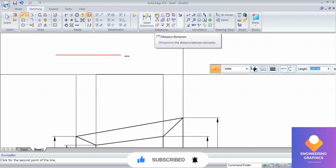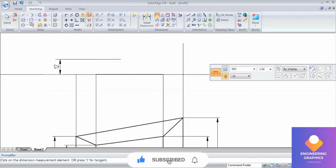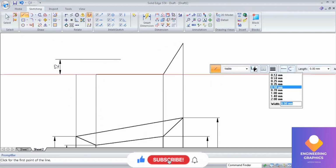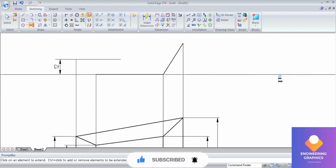Draw a line here. So go to distance between. We are getting 15.37. We'll change it to 12. So now we are getting the exact length here. Now we'll join with the thick line. Yes, we are going to join with the thick line.